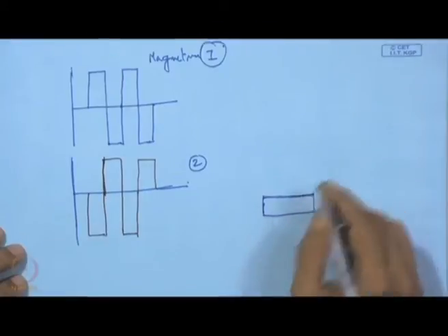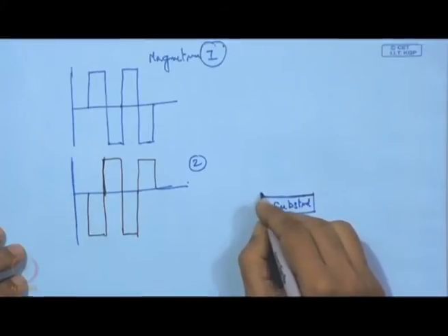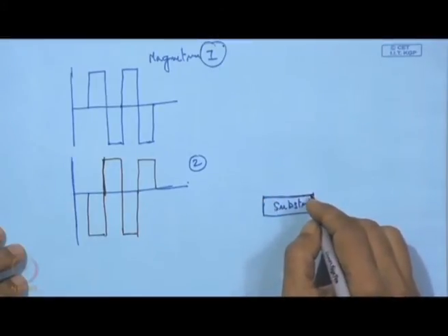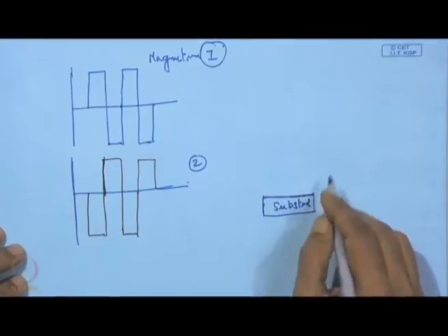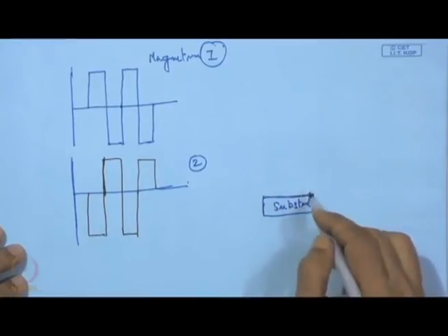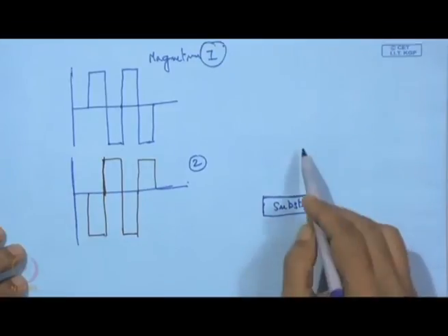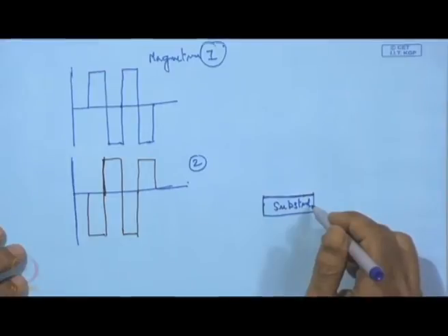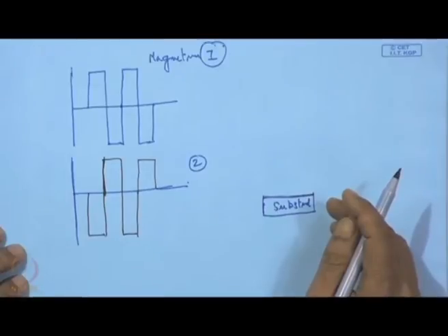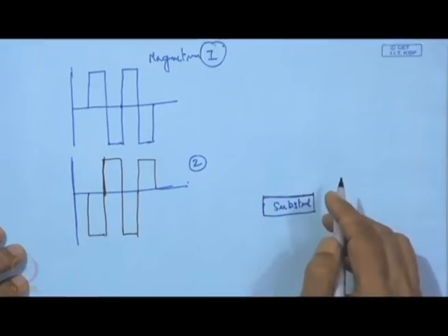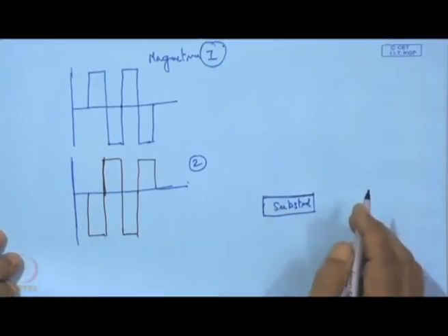For a conducting material substrate, a DC would be sufficient, but when it has a deposited film of non-conducting material, then one needs this RF or this DC pulse supply. So, this is true also for RF sputtering. Once this non-conducting material arrives and covers the whole surface, it becomes almost like a non-conducting substrate, and a proper arrangement has to be made so that we can have such biasing.